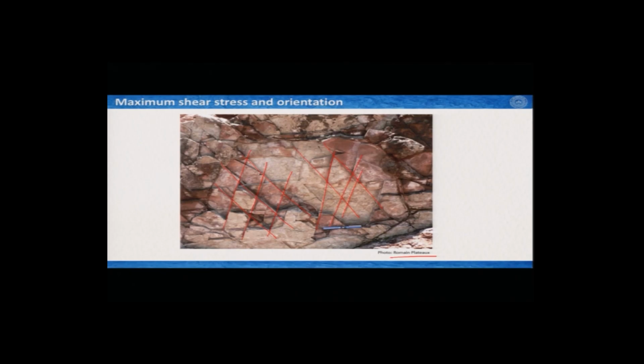Now, it is wise to imagine that these intersection lines, because these are planes, is one of your principal axes of stress and directions, and therefore, if I consider this, these 2 are your other principal axes of stress. So, I do not know which one it is, but if I consider this one which is projecting upward from the board, if it is sigma 2, then you can consider this one would be sigma 1 or sigma 3, and this one would be either sigma 3 or sigma 1.